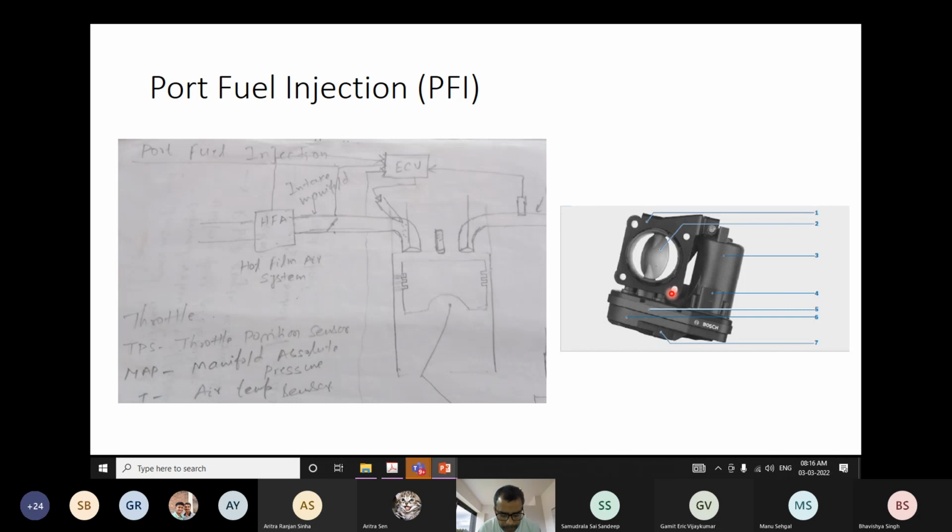So when we have a torque based demand or calibration map, the acceleration signals first of all go to the ECU, and then the ECU decides the throttle opening based on the user requirement and the power that may be required for other purposes. Accordingly, the throttle is opened. So that is what happens. I hope this is clear now.